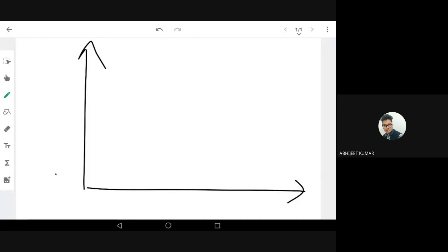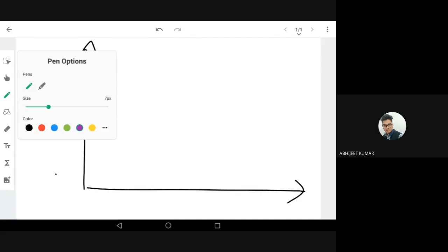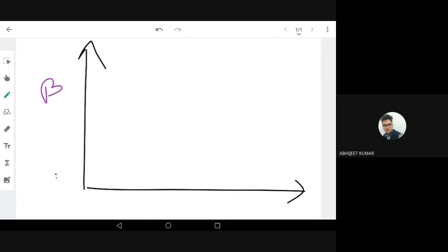Here, if I draw the beta, for example, I'm giving a sample of beta. This is beta, the DC gain, also called DC beta or hFE. If anyone has seen a data sheet, there may be a term hFE. This is also nothing but beta DC gain. Based on the IC, beta can also vary. I'm just giving a range. For example, my beta is ranging from 50, this is 100, this is 150, this is 200, and this is 250, something like this.